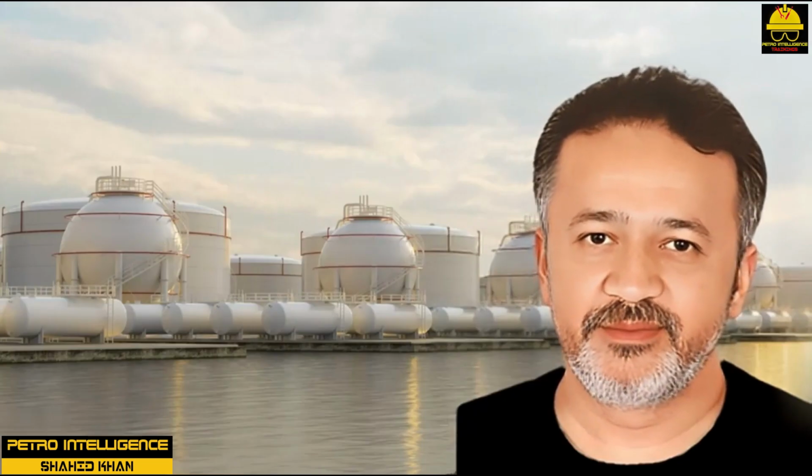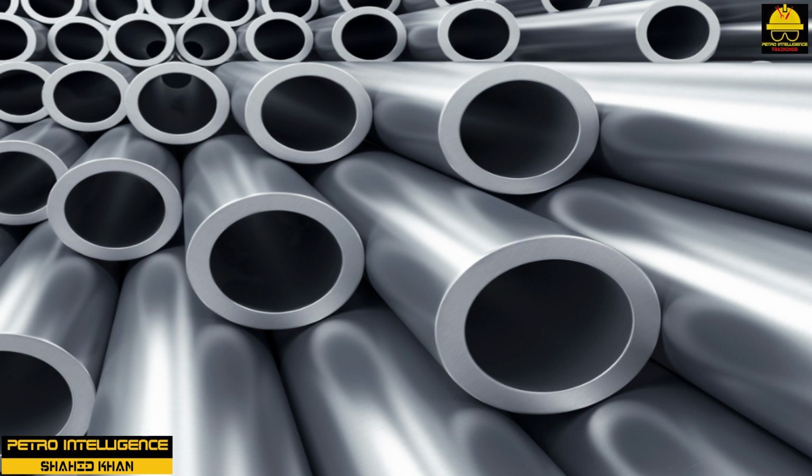Low-alloy steels. As the operating temperature of equipment increases above 650 degrees Fahrenheit or 343.33 degrees Celsius, the strength of low-carbon steels decreases. This decrease in strength becomes very pronounced between 950 degrees Fahrenheit and 1000 degrees Fahrenheit, or 510 degrees Celsius and 537.77 degrees Celsius.